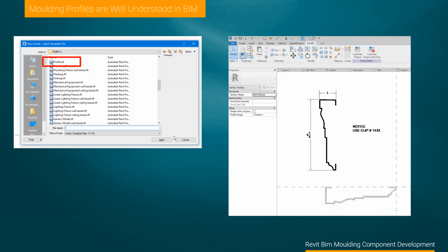I want to take note here that I could not just use this profile without doing some modification to it. So that's important going forward. I think it will be valuable for you to create Revit profiles of all of your DWG files for your customer to avoid some problems that might actually just frustrate them, take a lot of time, and or make them give up.